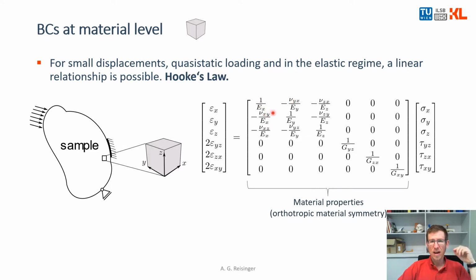These 2 numbers are equal, so we have in total 9 unknowns, 9 material properties for the linear elastic regime, only when we talk about stiffness. So I'm explaining this to tell you what the problem is here. When you have a generally shaped sample like this potato, you load it somehow. You have a distribution of stress and strain, and the material properties are hidden deeply in there, in a way that makes it actually impossible to determine them, even if you know the stress and strain state